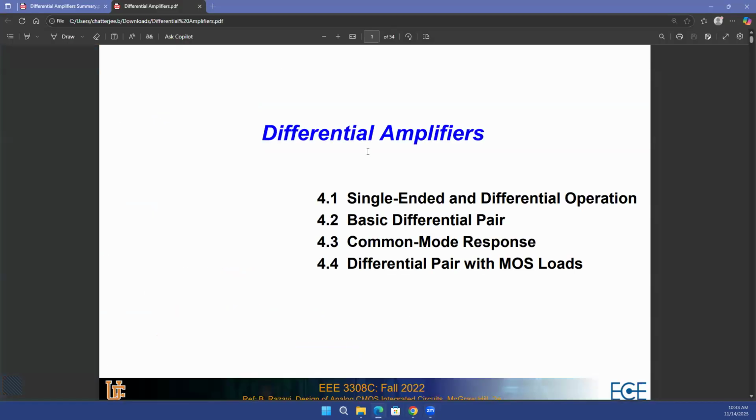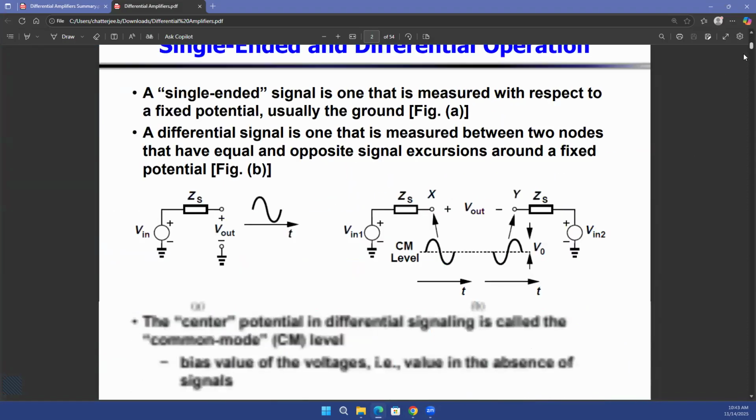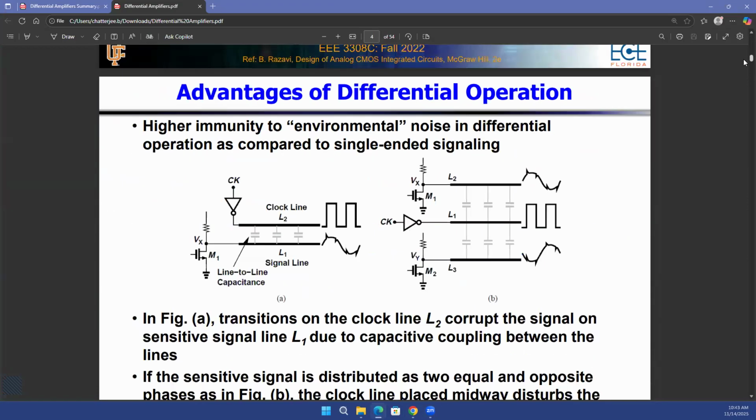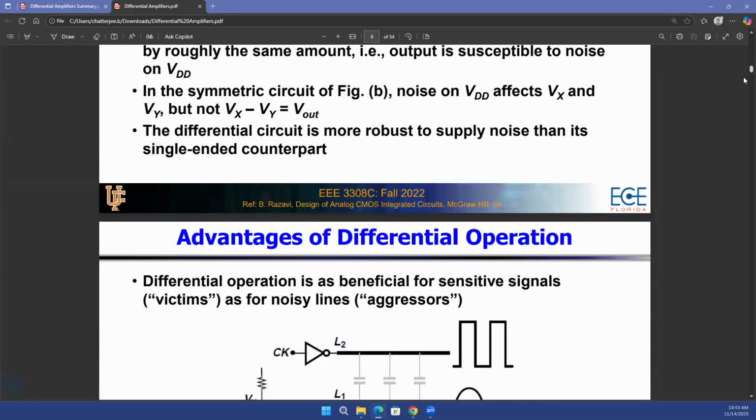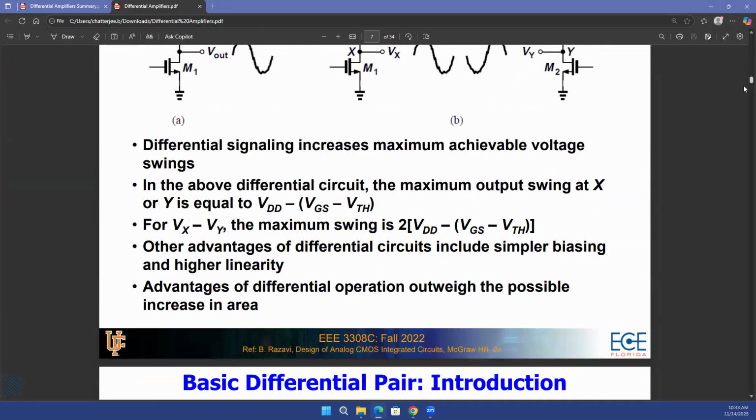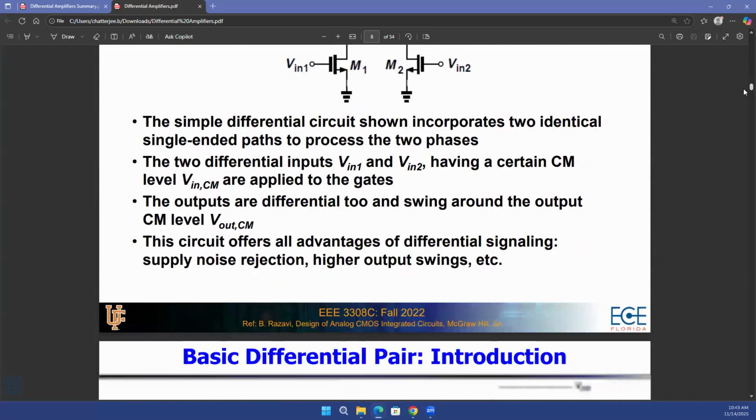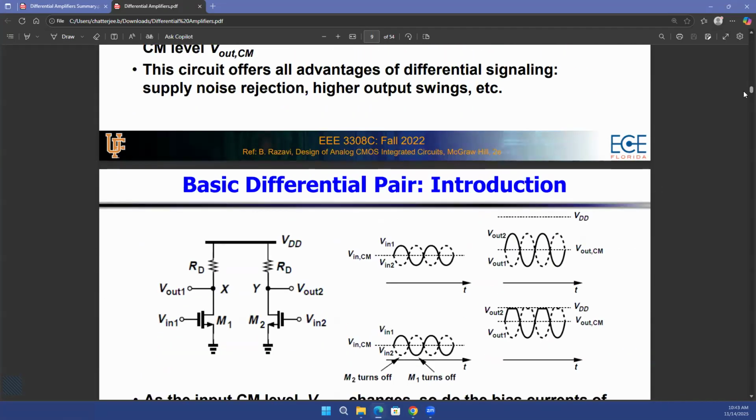All right. Now, in terms of differential amplifiers, last day we looked at how a differential amplifier looks, what the voltage swings at its output would be, and what the conditions are for which the transistors will be on and in saturation. Because of that, you already know that the transistor needs to be in saturation if it is to operate as an amplifier. Now, speaking of digital circuits, which you will start next week, and also because of your Lab 7, you will see in digital circuits, the transistors do not need to be in saturation.